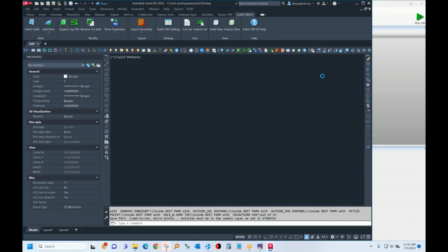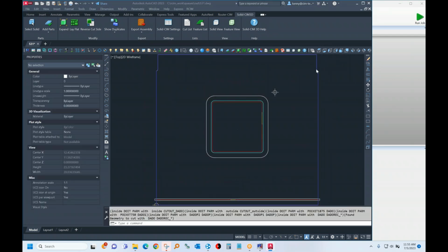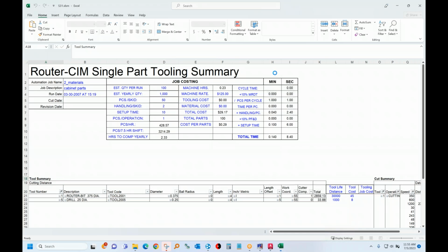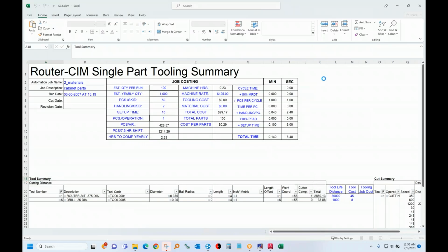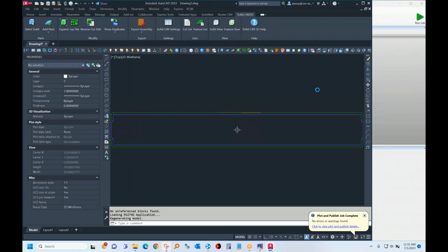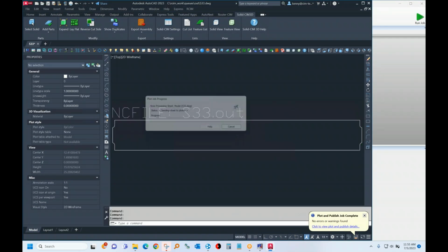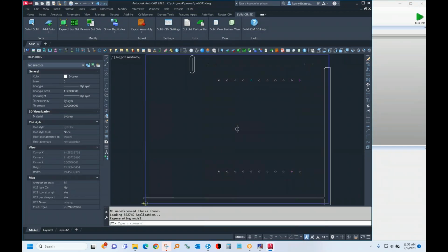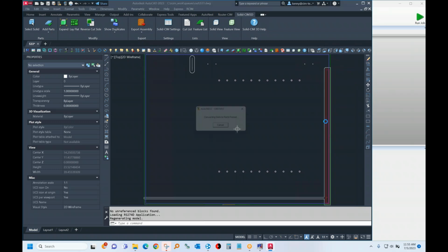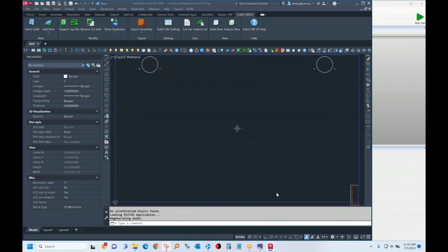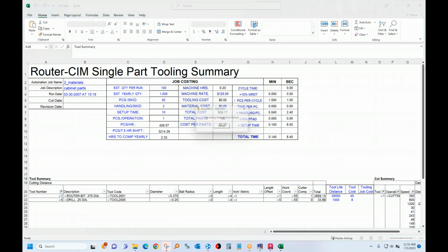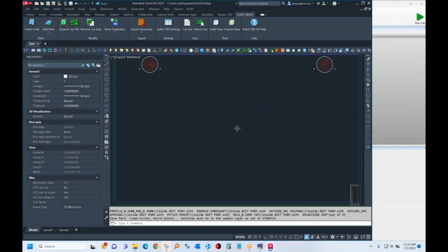Now, my pocketing knowledge, I'm using, I think, a 1/4-inch bit for the pocketing, and the slot may be smaller than that. So in some cases, I might need to have a special type of pocketing knowledge for smaller pockets than for larger pockets. And you could do that because the name of the pocket can indicate the width and so forth. So I see this slot right here is not getting fully pocketed. It's because of the tool knowledge I have. It uses a larger tool that can fit in between there. And you could set that all up.